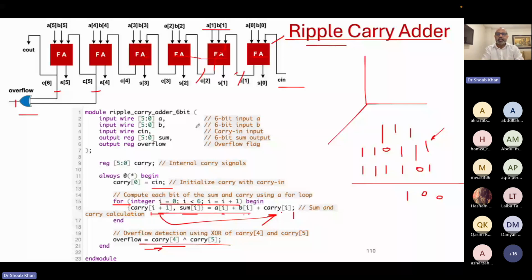And so this is a bit of a slow adder. And so people have come up with so many different ways to accelerate the process of addition. And again, please remember that there are two things that I want to do with this. First, tell you how you are exploring the design space where you can minimize area or put more silicon and get better results as far as the performance is concerned, because mostly people are concerned about performance. So now you say, no, I don't want to put a ripple carry adder. Let me explore other adders.